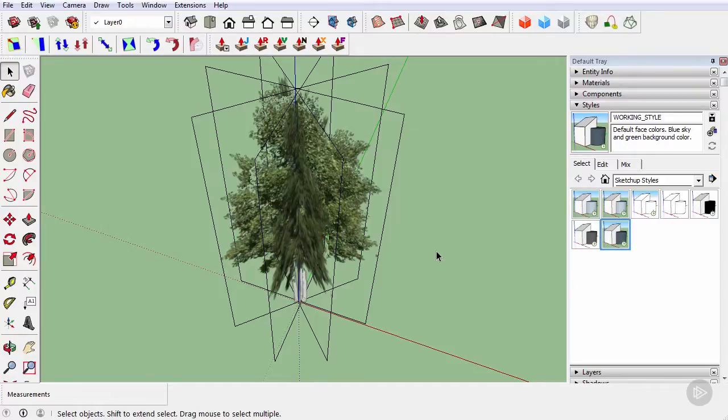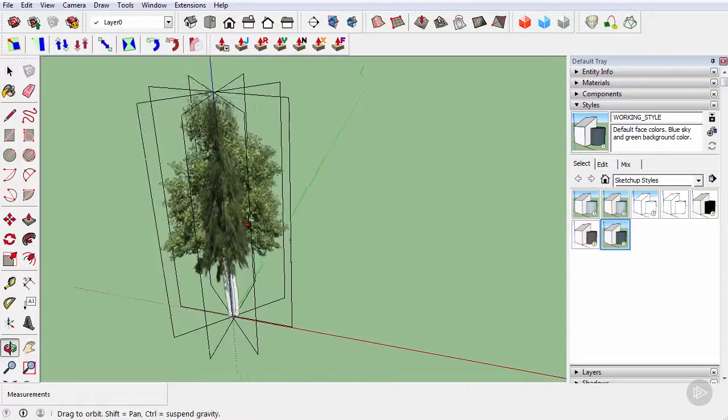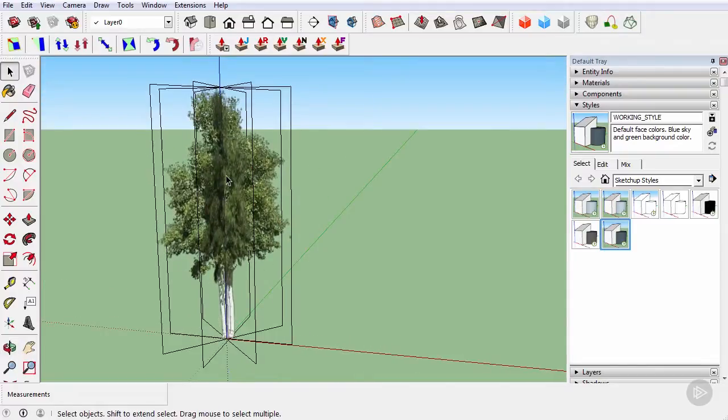So you need to make it a habit to center all of the geometry that's in the components that you download. So now let's take a look back at this and ask ourselves a very important question. Does this component satisfy my two sets of requirements that I have for components? The first set of requirements that I have for this component specifically is to provide me with a low poly 3D model that I can use in my terrain, and that I can also use to model shadow directions. So yeah, it does satisfy that.